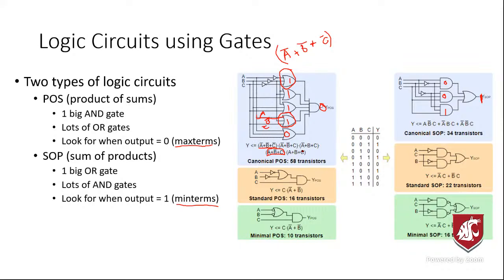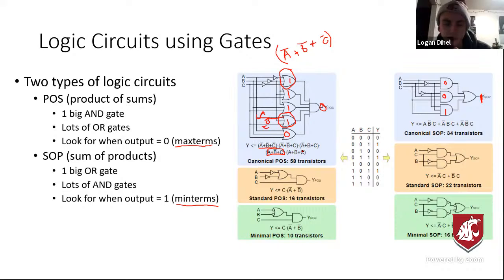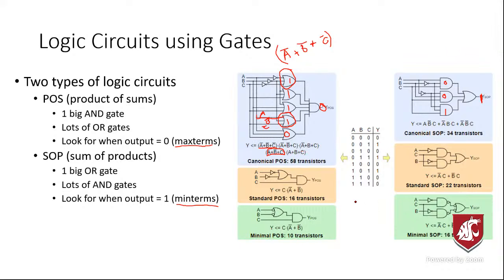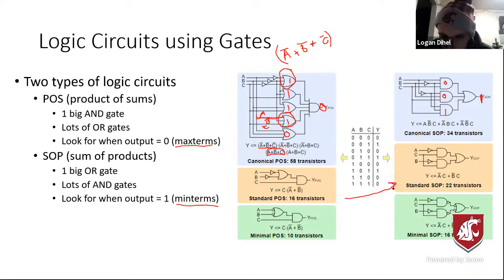That's basically just the key that you need to minimize the circuit. Yeah, exactly. So once you have the K-map, you're golden. One more thing I forgot to say: you'll see that we minimized these. These are both minimized SOP and POS circuits, but in this example, the POS is better. That was kind of dumb luck. It depends on the circuit. You really don't know what it's going to be at first.